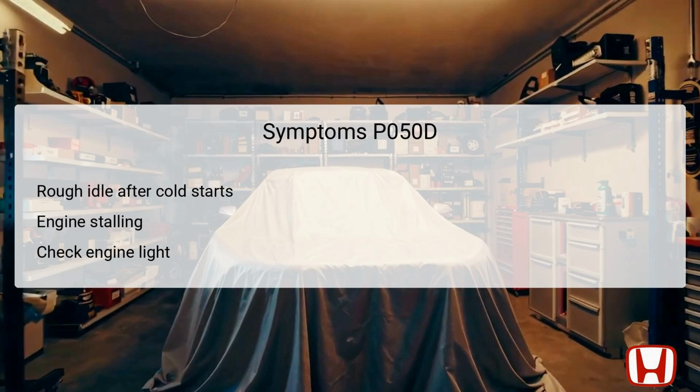Symptoms associated with DTC P050D primarily revolve around difficulties during the initial cold starts. Drivers may notice a rough idle, where the engine fails to maintain a consistent speed, or may even stall entirely. This behavior is concerning, as it indicates that the engine is struggling to achieve the necessary operational conditions.